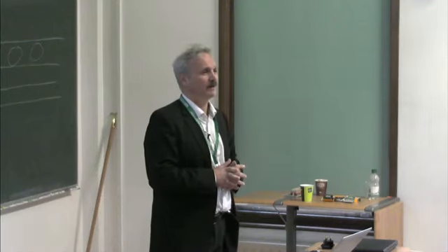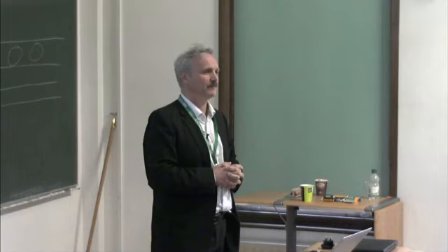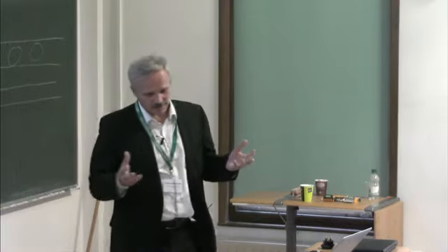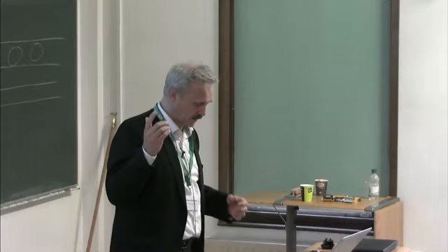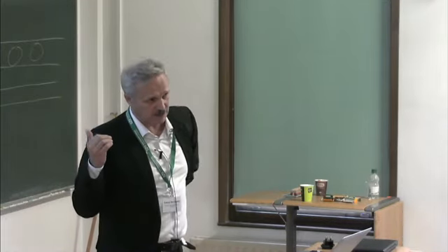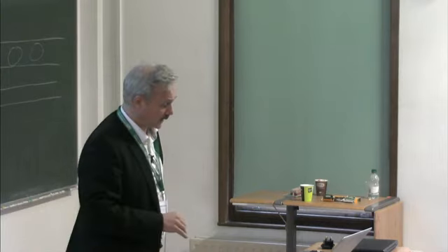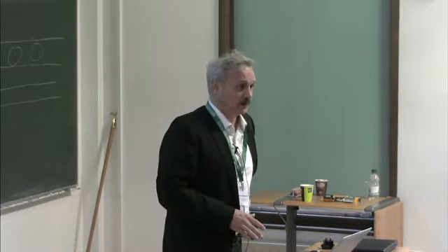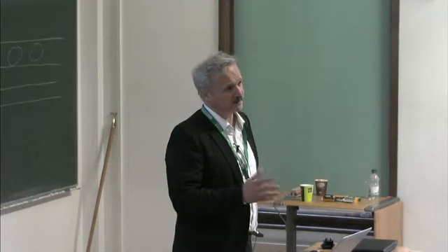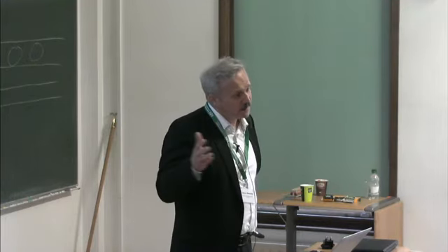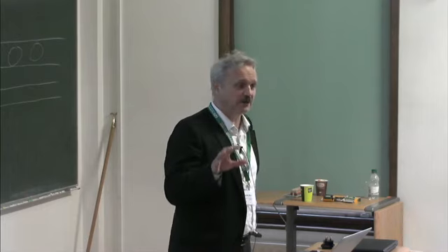I'm a bit puzzled with the dispersion relation that it shows, because it's for the free surface, right? Yeah. But from the schematic presentation of the problem, I had the impression that at the free surface you also have the ice. Yeah, I have floating ice, but in all the photos I showed, when we did measurements from the floe, the ice thickness was 30 centimeters. The elastic modulus measured from the test for flexural strength was 0.3 gigapascal, and the wavelength was around 100 meters. So then this term was very small.